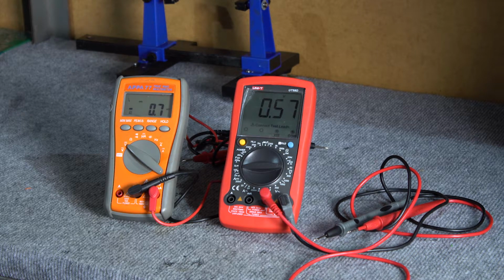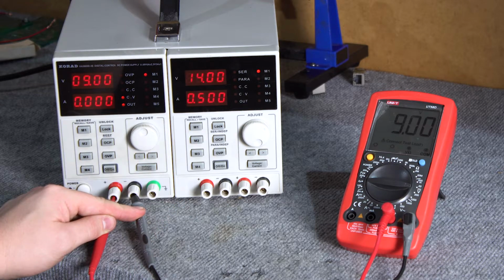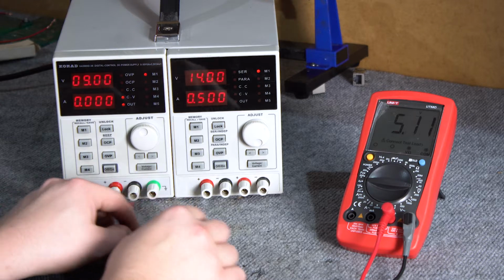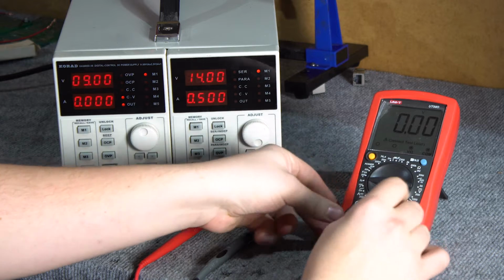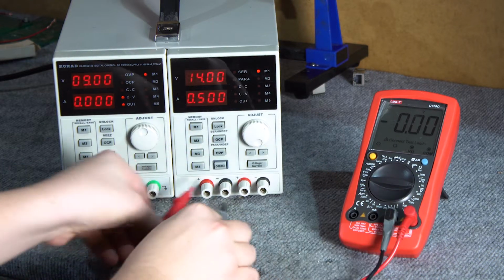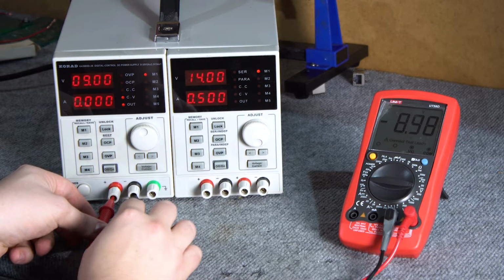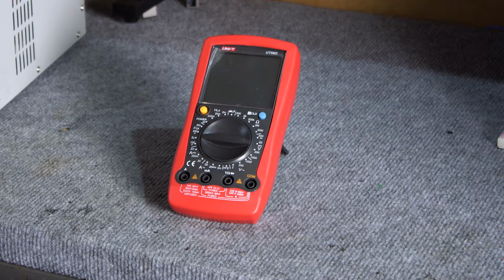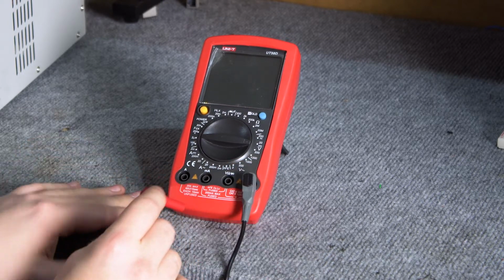This resistance reaches 10 mega ohms and more, even 100 mega ohms. If you turn the probes on the opposite side, you will see a minus sign with direct current at the same value with the alternating one. However, when we make a mistake and turn on the voltmeter in a series, it is possible that the system will not work at all, because such a large resistance will make the current flow so low that the system may not be turned on. Always take special care of the probes to be connected to the COM terminals and the voltage measurements to V.